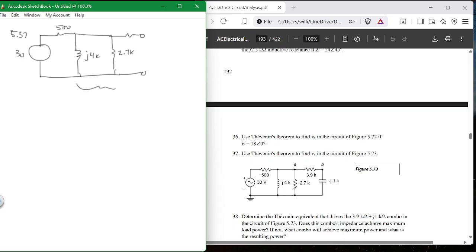Note the word usual. 1 divided by (1 divided by 4,000 I plus 1 divided by 2,700) equals, option 1, argument down, equal, and then shift equal. What is the combination of these two? It's 2237.89 at angle 34.01.